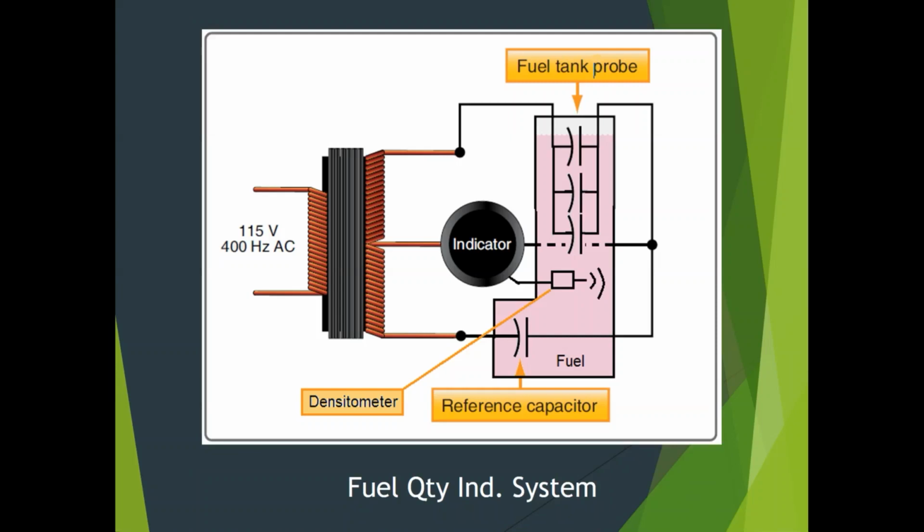And then as it continues to drop, now another one might start to be out of fuel, and then as it continues to drop, now the inboard one might be out of fuel, right? It's going to come down the inboard one. So your inboard ones tend to be submerged the longest. Sometimes the fuel will be getting lower on the outboard one, and then it'll start to come down the inboard one, right? Because these are sloped tanks.